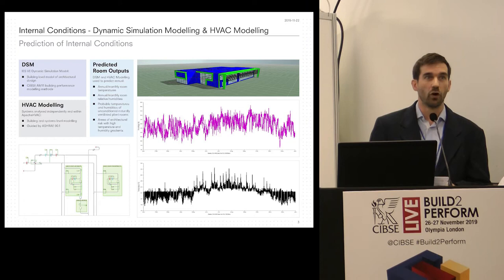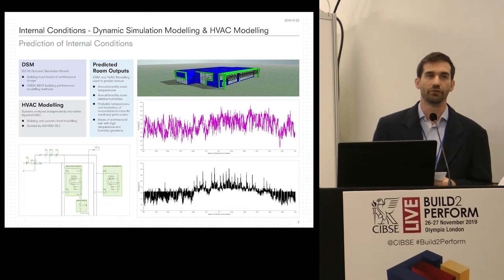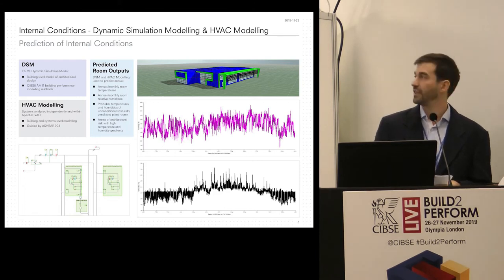So the big question is how warm and how moist. I used building simulation modelling and HVAC to predict the room temperatures and room humidities. This captured latent gains and the latent impact of cooling cycles and air recirculation through air handling unit chilling and dehumidification impacts. This was used to predict the room temperature and room relative humidity, which were then used as inputs into my condensation modelling later in the process. This allowed me to calculate the critical surface temperature for the avoidance of mould growth, condensation and other related damage.